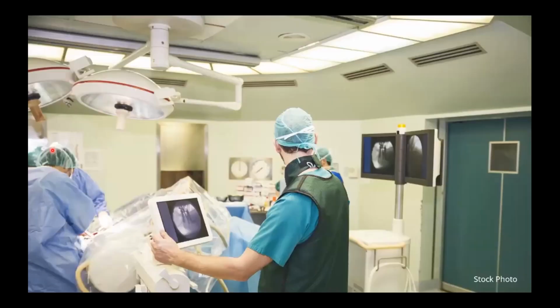So here we see another operating space. What I see here is linear slot diffusers located and angling on the outer transition to the ceiling. So these are linear slot diffusers, much like we provide in our GRD products. However, they are high mixing, and the way they're angled, it looks like they're discharging directly into the critical zone. And looking up at the ceiling, I do not see any laminar flow diffuser. So according to ASHRAE 170, this would not be compliant.